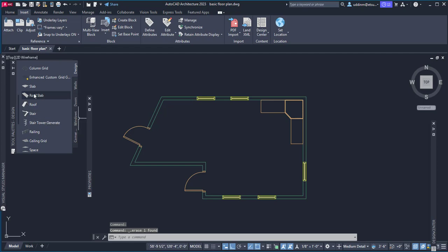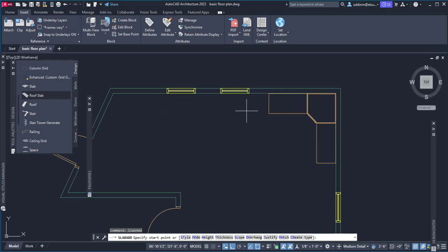So at this point, you want to find your slab option, and as we said before, when you are going to identify the corners or identify the boundaries, you have to make sure it's totally enclosed. So where you see this little green box here, typically you want to start on that little green box and you work your way around and enclose this same area here. So what I'm going to do, I'm going to start here, come around to the back side here, front side here.